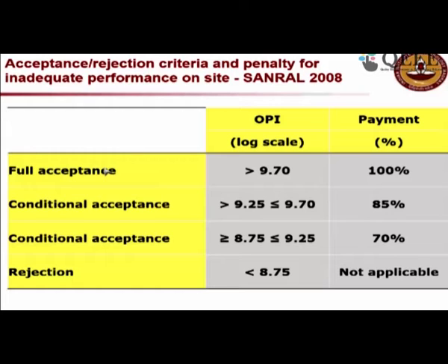For example, in this slide, what you see is a condition in the contract document itself. This is an example from a project in South Africa where they have actually adopted this. The oxygen permeability index, or OPI: they said they will measure the oxygen permeability index on the concrete structures after the structure is built.